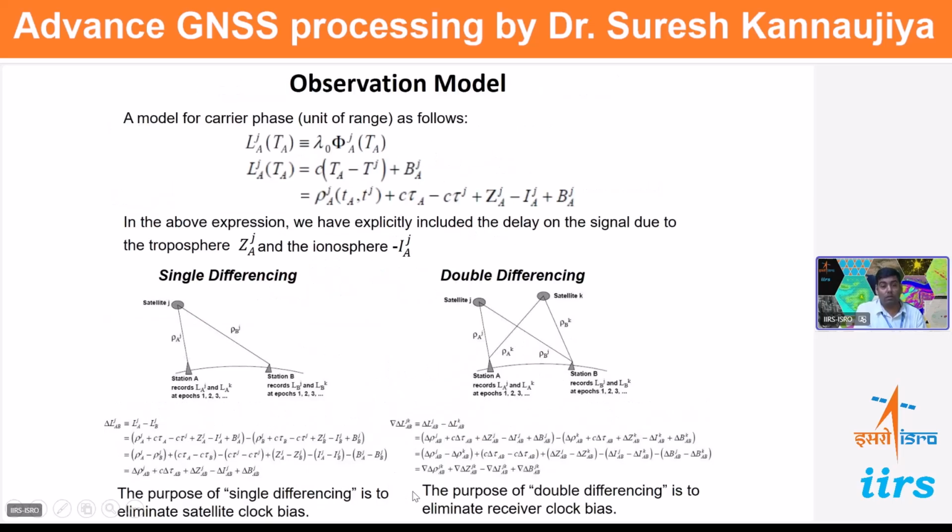When we use this fundamental equation for length estimation, the length between the satellite and the antenna, this is our objective. When we are able to estimate the almost true range between the satellite and antenna, then we can think of millimeter accuracy estimates through the fundamental equation.